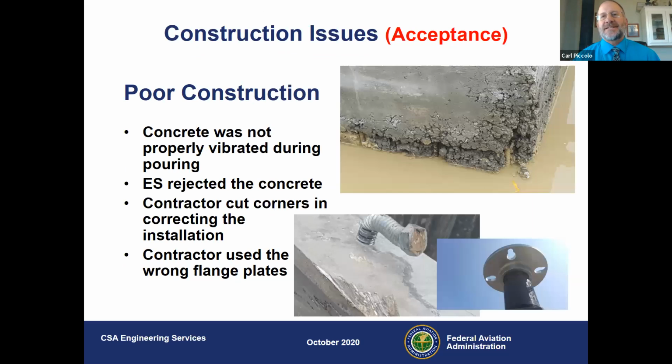Here's an acceptance issue. This is a foundation for one of our lighted nav aids. When the contractor poured the concrete, they didn't vibrate the concrete properly. You can actually see the structural steel inside this concrete. This is not an immediate threat to the NAS. The problem is this concrete is going to fail within a number of years, and we're going to have to be out there rebuilding this foundation. Our REs will make sure that the concrete is poured per our standards, et cetera, to make sure that these facilities will last the number of years that they're intended.